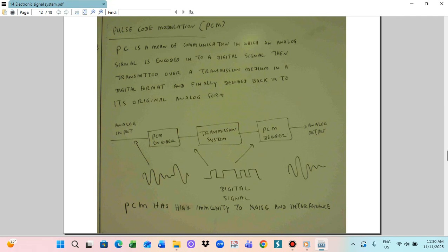Noise and interference can be eliminated. When making a control system, the important thing is that the control system must be free from noise or interference. Some control systems are very important and very sensitive, so any noise interference can damage the overall operation and main functioning of the control system. Although we are using shielded wire, which can protect against electromagnetic interference, it is not always 100% satisfactory. So not only do we utilize the shield and protection wire, we also have to utilize the pulse modulation system. Instead of using the analog, we convert it to digital, and then we transmit the digital, and then we can decode that back to the analog. By this way, we can more effectively utilize it for the process control system.